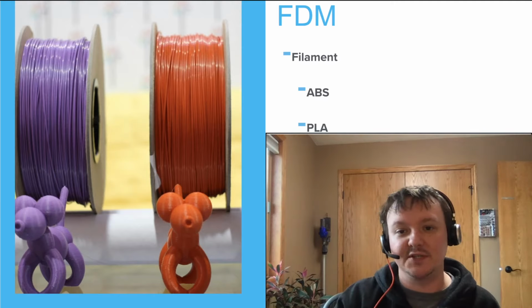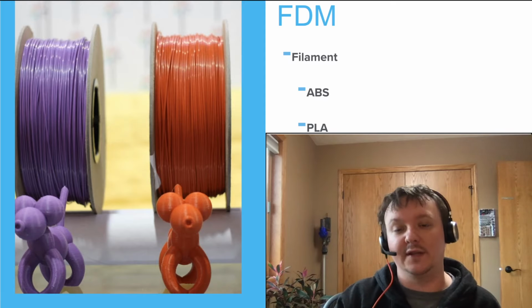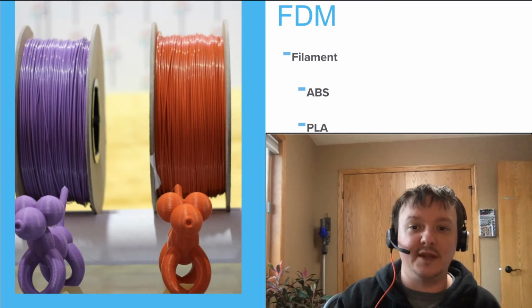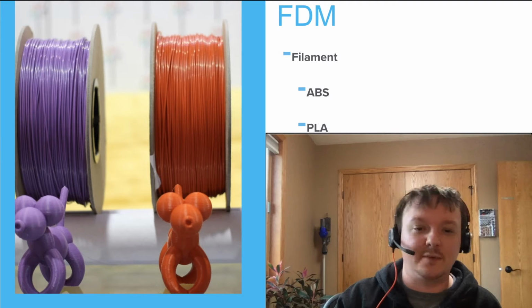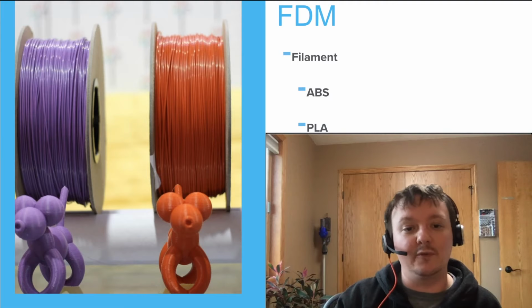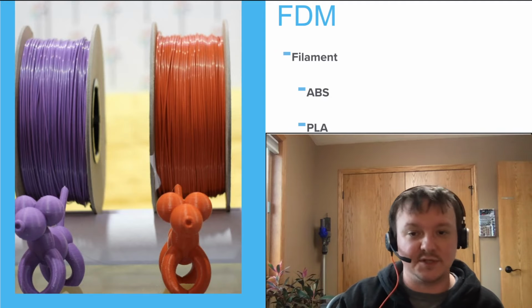So if you're printing something, it will usually be higher quality out of PLA, but it is nowhere near as resistant to the elements or heat as ABS. That's the main filament. Primarily, what I will print with is PLA, just because it's so easy and it's definitely the cheapest of the options.